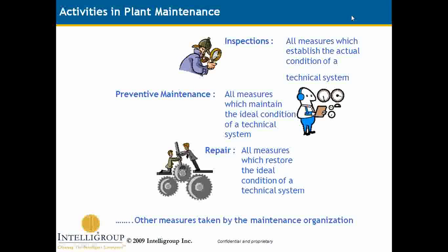And preventive maintenance, as I explained yesterday: every piece of equipment has manufacturing guidelines. If you take a motor, at regular intervals the bearings have to be replaced, greasing has to be done, or vibrations have to be measured.